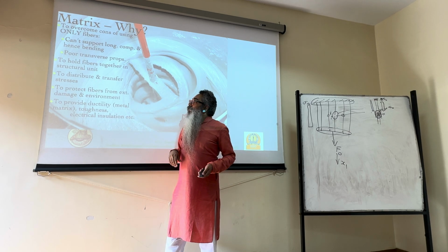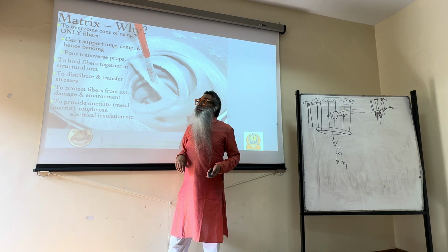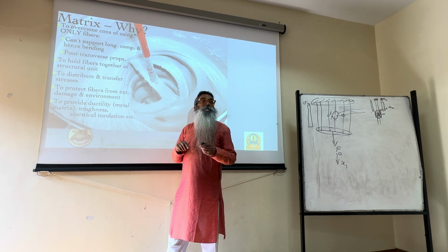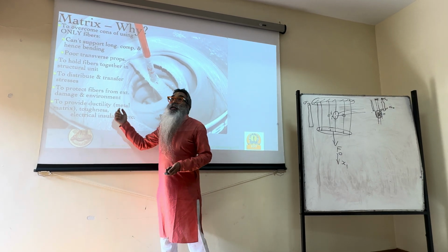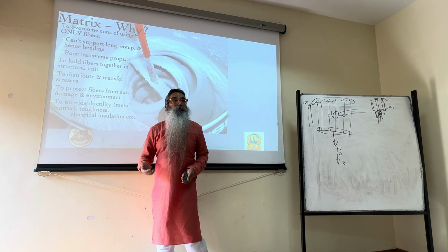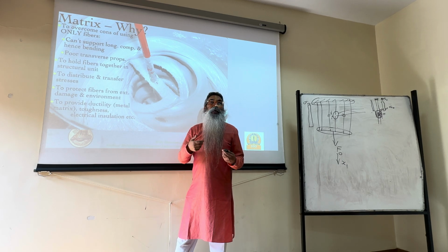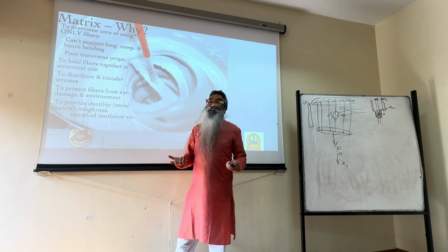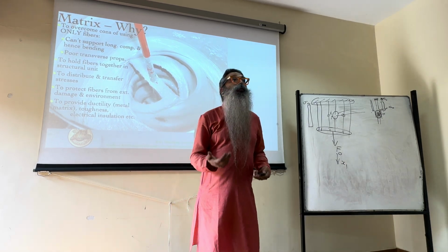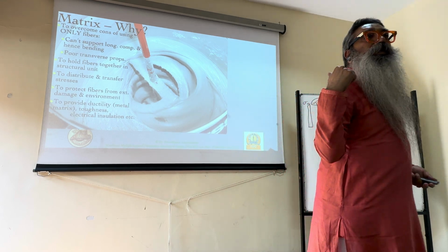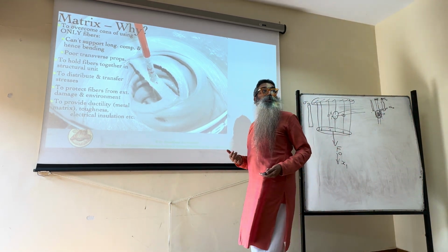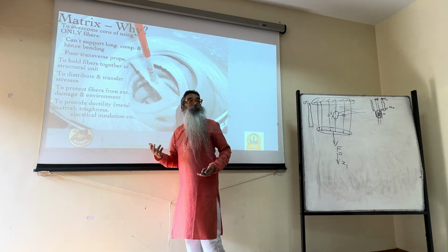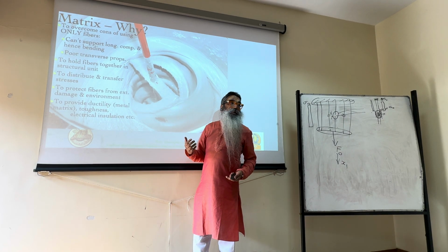So when you have metal matrix, then unlike polymer matrix, which are brittle, the metal matrix, just like any metal or metallic alloy, is ductile. So you can get the best of both worlds. You can get those ductility aspects of the metal as well. But metal brings in higher density, so the weight advantage that we were getting with polymer matrices, of course, is not there. But the temperature capabilities, the ductility, and therefore manufacturability, etc., those things are there.